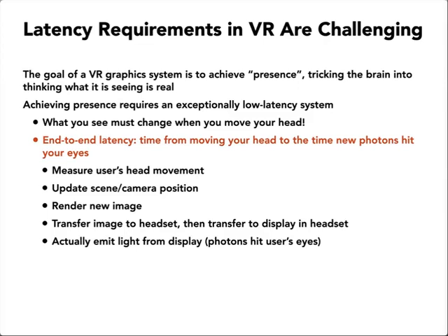Of course, a lot of headsets these days actually have the GPU on the headset itself. In any case, we then need to transfer that information from GPU memory, for example, through to the display itself. And then the display itself needs to actually physically emit the light from the display surface. And since speed of light is very fast, as soon as it's emitted, pretty much the photons that are emitted will hit the user's eye, so that speed of light time doesn't really contribute to the latency in an appreciable way. But the rest of this stuff does, and it has to do with measuring, computing data, and communication. So all the computer engineering stuff.